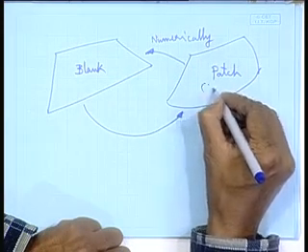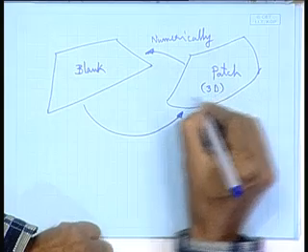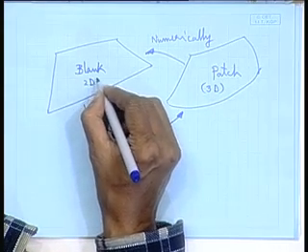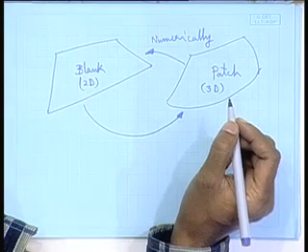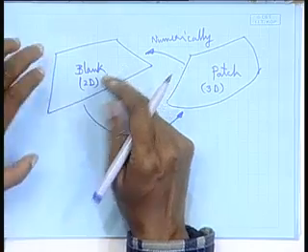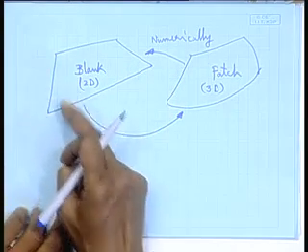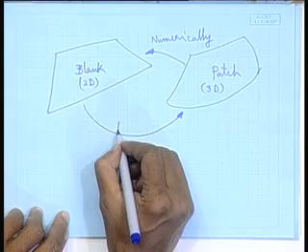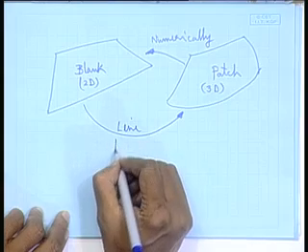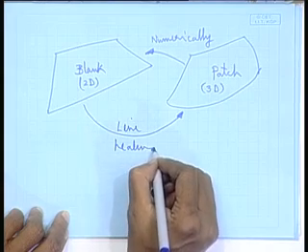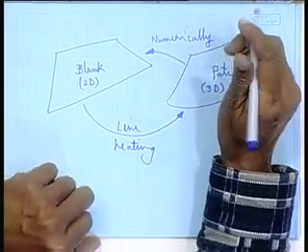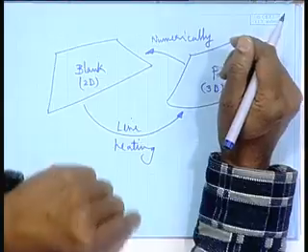This is my 3D and this is the 2-dimensional flat shape. So I have got this, and I got it cut from the steel plate. Now to this I am applying line heating. This technique is referred to as line heating. Why? Because the heating is done along certain predetermined lines. That predetermined line is the pattern of heating.